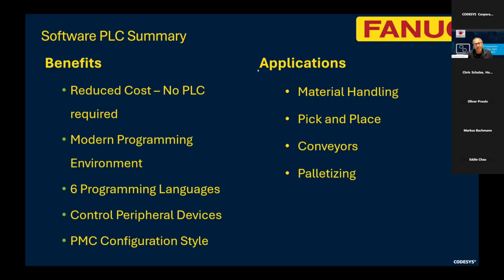It also gives you the ability to control peripheral devices and execute programs. And again, since this is closely aligned to PMC, there's not a major obstacle in learning. That is, people who are using PMC today will be able to slide right into the CODESYS development system smoothly. And if they choose to still stick with the ladder programming, they'll still have that capability. In terms of applications, this is going to be ideal for material handling, pick and place, conveyor control, and palletizing, and a lot more. But wait, there's more.